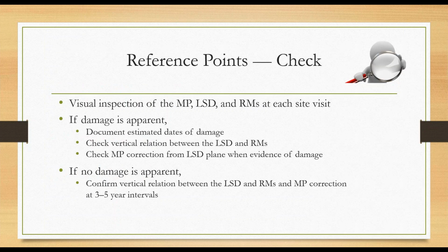We do require that reference points are visually inspected. These are the land surface datum, measuring points, and reference mark at each site at the site visit, documenting any changes that you might see. If damage is apparent,